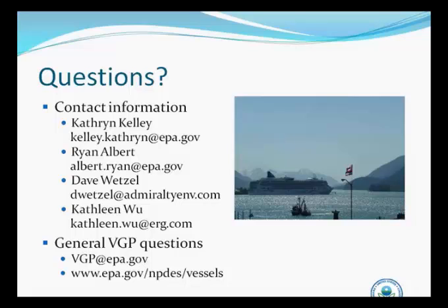And it should indicate how much of the hold time it did exceed. Your other option, of course, is to have the lab perform the analysis for you again for free. You'll have to, of course, collect the sample, get the equipment, and redo all that stuff yourself again. But you should request that they perform the analysis again within the hold time.